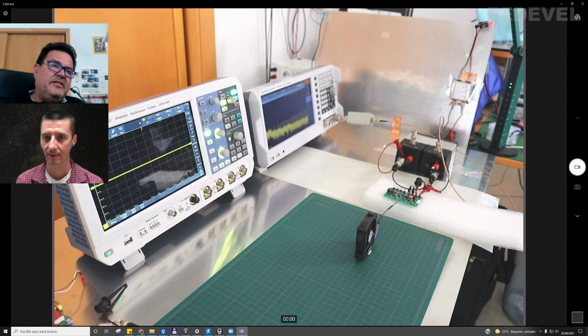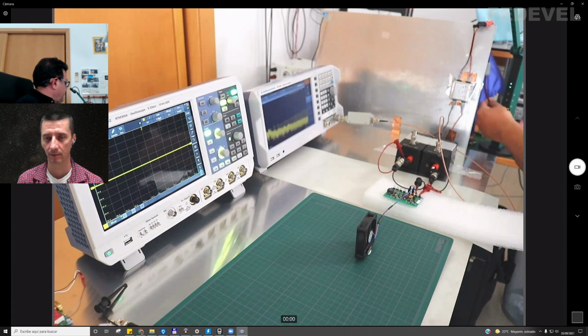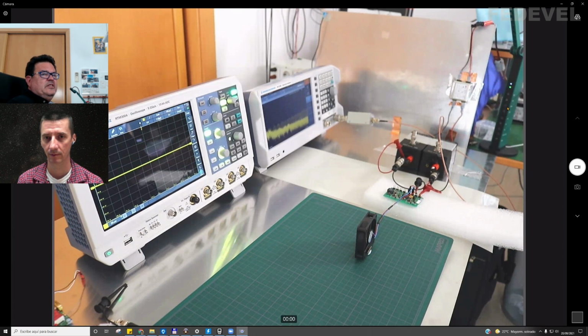Okay, so later you see this. What is this? Really, this is not necessary, but I usually work with this kind of filters because I want to avoid the noise that is coming from the power supply or from my laboratory, or that is picked up by the cables. You can see, for example, that in my cable, I have a ferrite in common mode. I have more ferrites here. You can see, I have more ferrites in the cable.